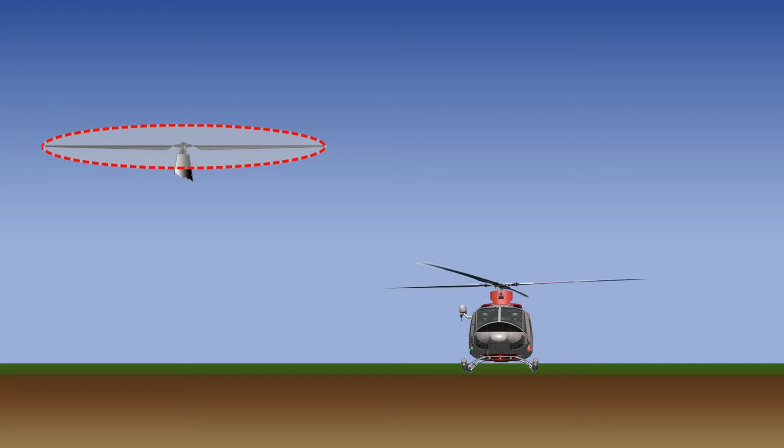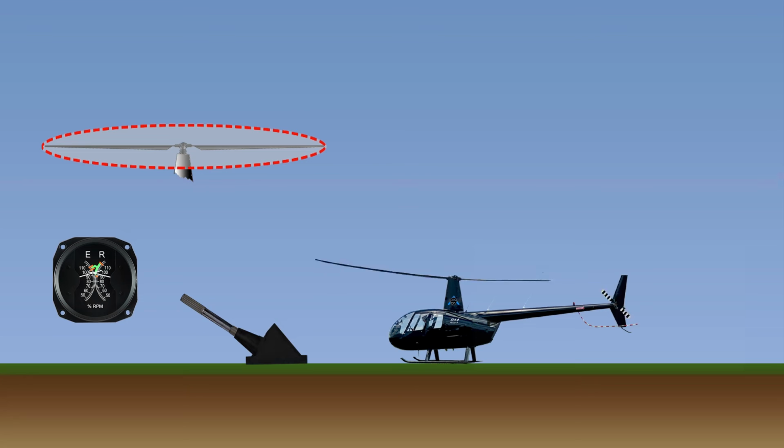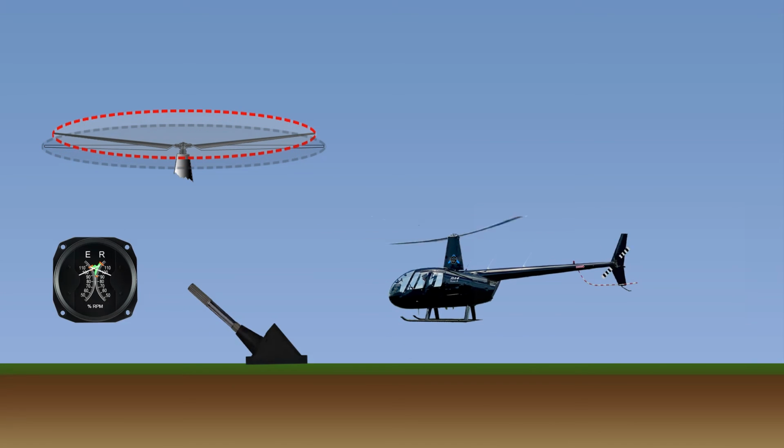The rotor blade rotating about the rotor hub possesses angular momentum. As the rotor begins to cone due to G-loading maneuvers, the diameter of the rotor disc shrinks. Due to conservation of angular momentum, the blades increase speed even though the blade tips have a shorter distance to travel due to reduced disc diameter. The action results in an increase in rotor RPM which causes a slight increase in lift. Most pilots arrest this increase of RPM with an increase in collective pitch. This increase in blade RPM lift is somewhat negated by the slightly smaller disc area as the blades cone upward.